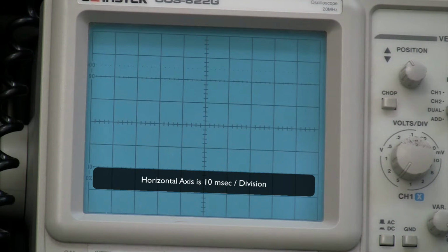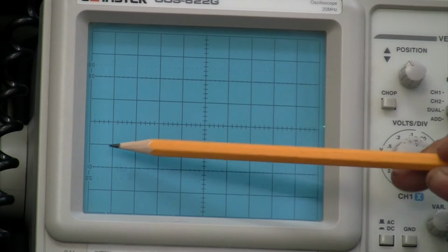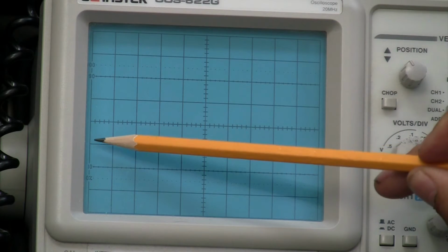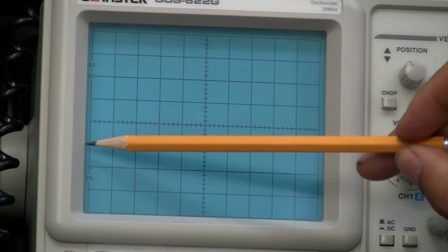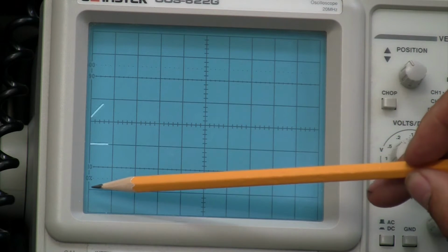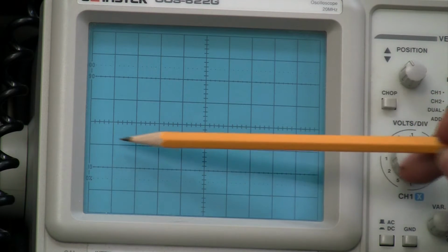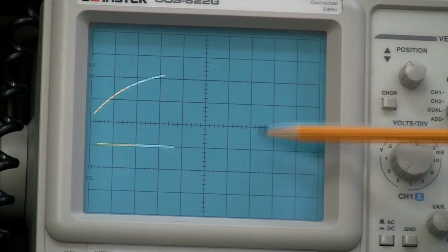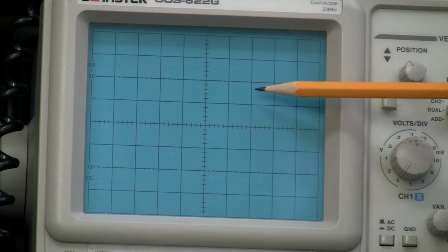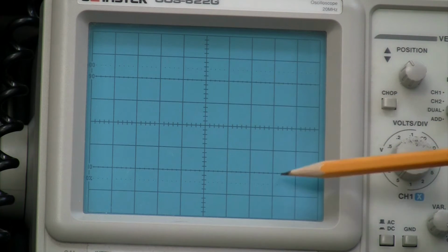Over here on the oscilloscope, we have two different waveforms shown. The bottom waveform is actually the output of the Q106 going from plus 5 volts to minus 5 volts. And the pulse width is adjusted so that the leading edge is right about here, goes for a while, and then it falls down. So by adjusting this falling edge, we're adjusting the release time of the Q109.